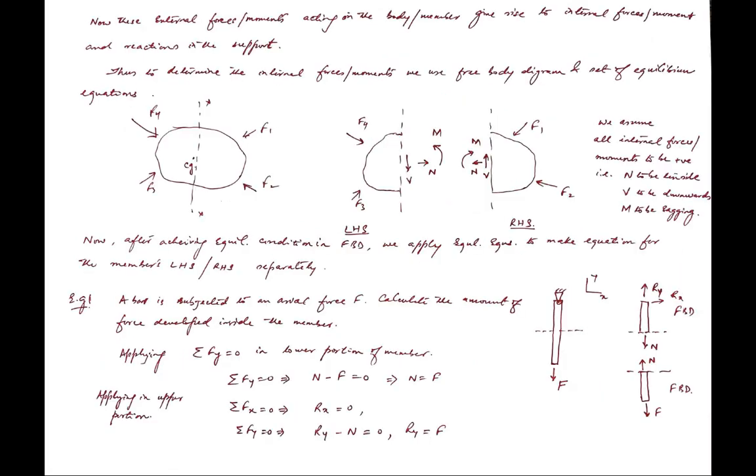For the sake of our calculation, and for finding the actual nature of the force applied there, you have to assume first. The force developing there can be tensile, or it can be compressive. So first of all you have to assume one thing, either tensile or compressive, and after the analysis we can say whether our assumption was correct or wrong. How do we do that? We will see.